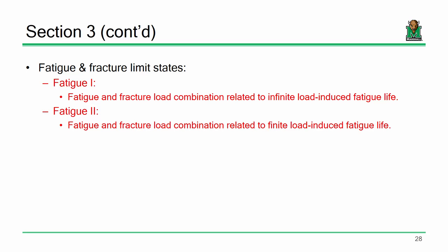There is a point, however, and we can start getting into the literature and into the data. There is a point when, I don't care how many cycles of load you put on it, there's a certain threshold stress that we say you can put 2 million cycles or 200 million cycles. It's still not going to be any more than 12 KSI.